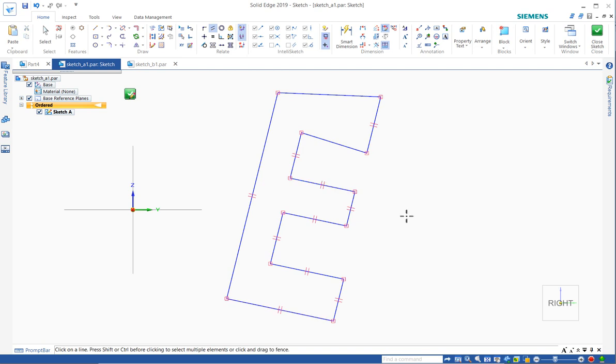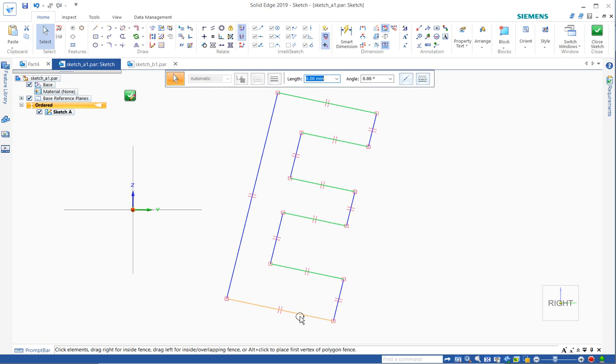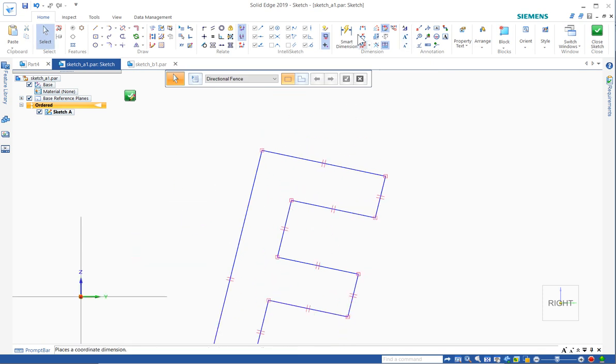Some of these I wouldn't necessarily do the way that they have you do it, and some of these commands have been improved in the later version. Let's see if we can illustrate that. I believe if we select this and hold the control key down and pick multiples, and then do parallel, I can do one target. So that's pretty cool. There's some other commands that work that way as well. If you hit the help docs, equals works that way now, and parallel works that way.